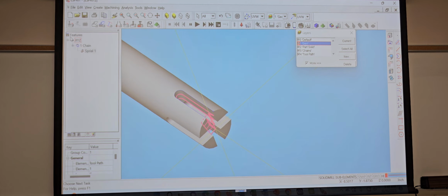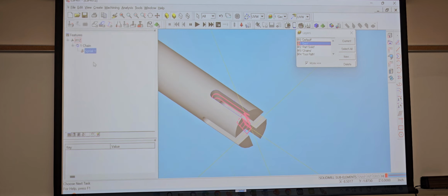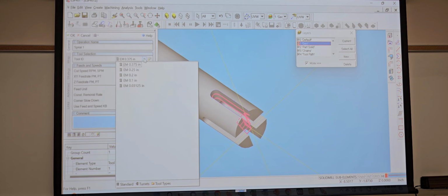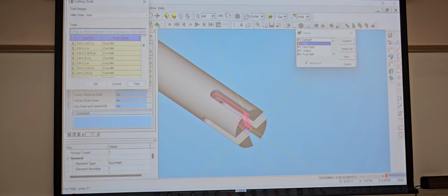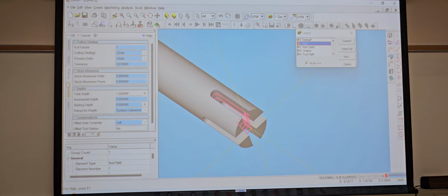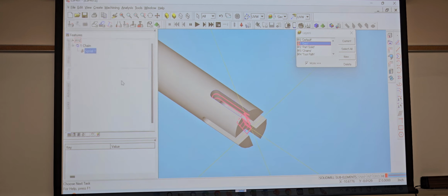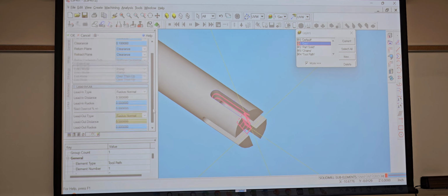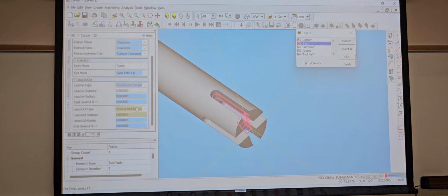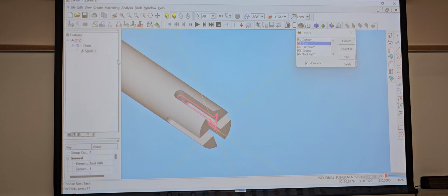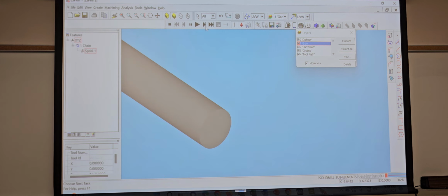Mine's just like either machining off to the side, machining outwards. Yeah, that's why I kept running into that, it goes through the part, it just became a big pain in the ass, so I just said, let me try it this way, and it seemed to work. So what were you saying about doing that? Where are you putting the work plane thing? Put your pockets in first, so you have a flat surface, and then when you click on the bottom of that pocket, and then you change your axis to that point, you know what I'm saying?